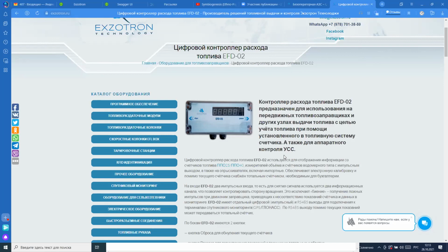If we want to achieve a situation where the data in the monitoring system one-to-one reflects the data submitted in the primary document from the operator or the tanker driver, it is necessary to oblige the driver or operator to write down the meter readings at the beginning of the day and at the end of the day, display the difference in the total counter, and check himself against these records, which he makes, in order not to make mistakes.